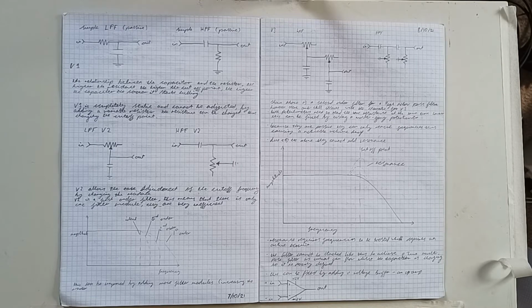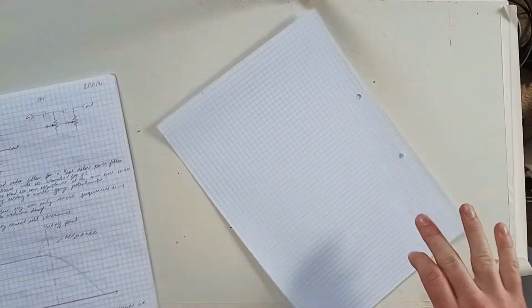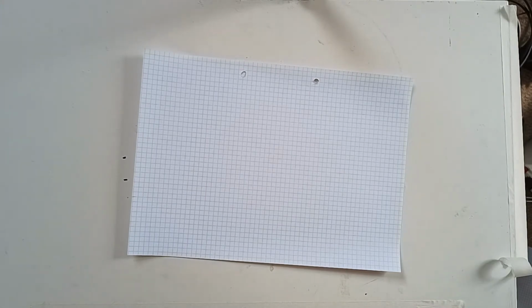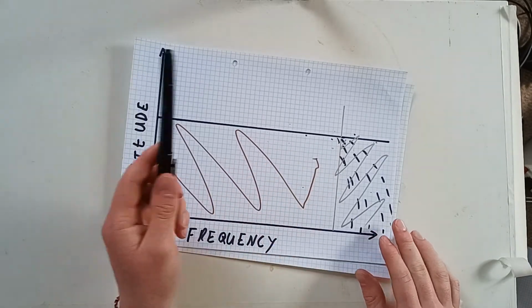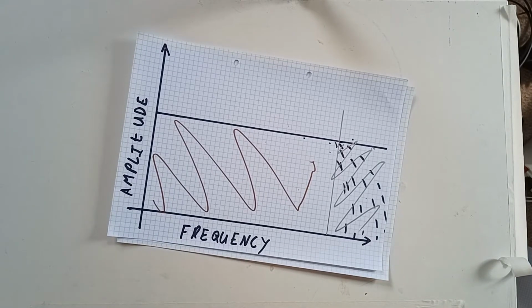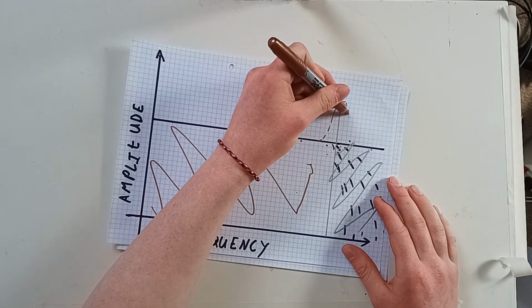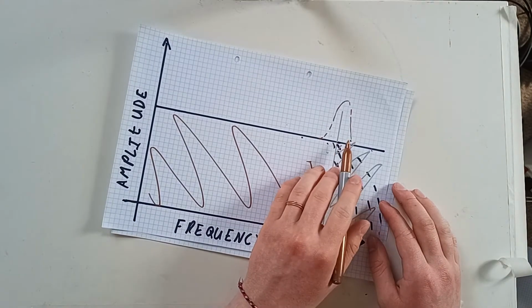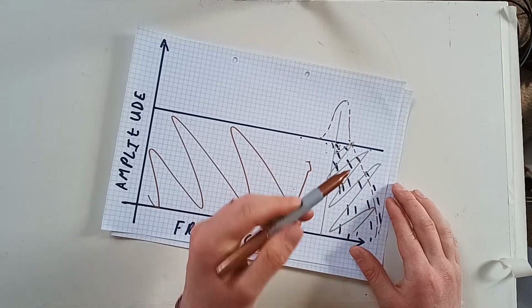The next thing I'd like to get onto is something called resonance, and that was the next thing I researched. Resonance refers to, or in this graph here, to go back to it yet again, this is the cutoff point. Resonance is sort of an emphasis on that cutoff point. So if you had a lot of resonance, you'd have a jump up in your signal around that frequency up to here, and then it would slope back down with the filter, like so.